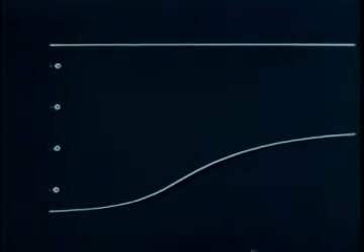In addition to moving from place to place, an elementary piece of fluid is generally squeezed or stretched and rotated as it goes. We are going to focus our attention on the translation, not on the deformation. In this flow of water through a contraction, hydrogen bubbles have been used to identify pieces of fluid so that we can follow their motions. These pieces are quite large, however, and we would like to examine the motion of very small, infinitesimal bits of fluid. Therefore, it will be more convenient to have a computer simulate these motions and generate the visual displays for us.